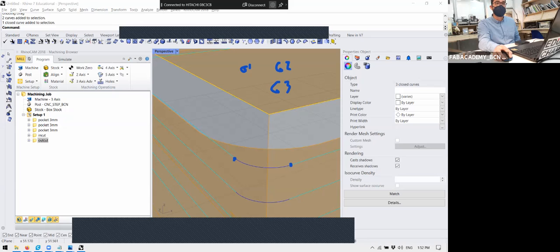So this one we can divide this line into a lot of millions of points and go point by point, more lines of G code, different settings on the machine on the accelerations, or we can calculate this as a radius that in G code is I, J, with a start of the radius, start of the arc. So how you interpret the geometries is what the post processor does. How to interpret the movements. Is point to point is the same as the robots. Point to point, linear moves or arc moves.